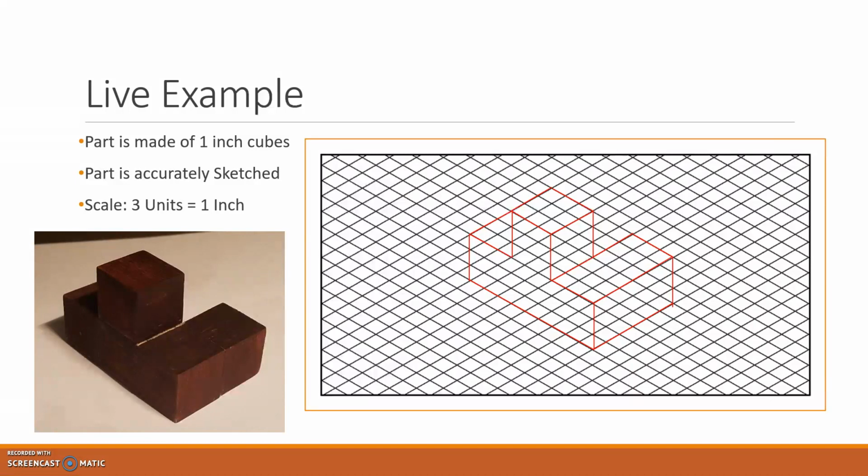The last thing I do want to point out is another line that you should never add is hidden lines. As you can see just across from our first defining line here, we do have where would be the line for the other side of this top cube. You don't add in hidden lines because you don't want to confuse whoever's looking at the object. You would save those hidden lines for 2D sketches that go more into detail of how everything is supposed to be laid out.